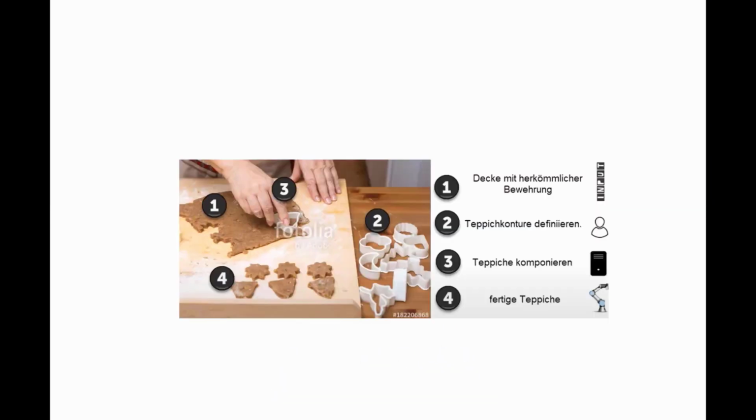We first determine our reinforcement and then punch the carpets out of the already laid reinforcement, so to speak. That means the program recognizes within the geometry of the carpet which bars should be contained therein. And this I will show you in a video.